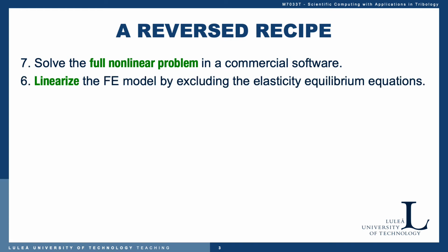Now, to do so in a rigorous manner, we had to linearize this model. And if we now view the model as we did before, we have the linear elasticity equations that model the deflection, the deformation in the segments and the collar, and this is now causing a fluid structure interaction also, and non-linearities due to this.